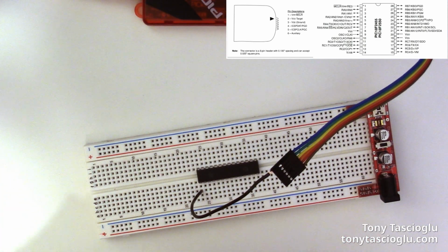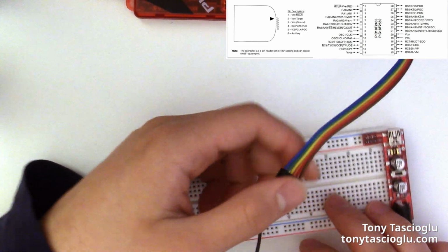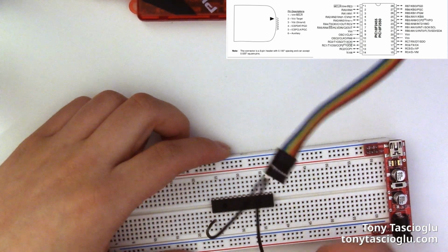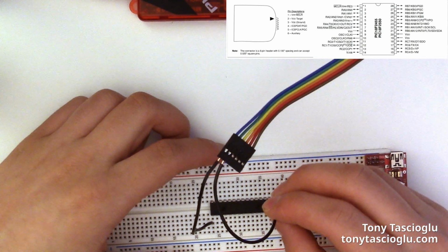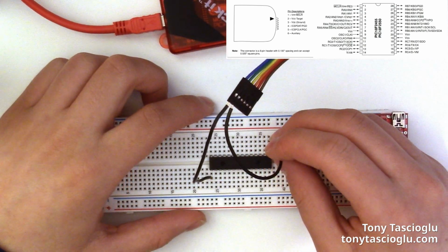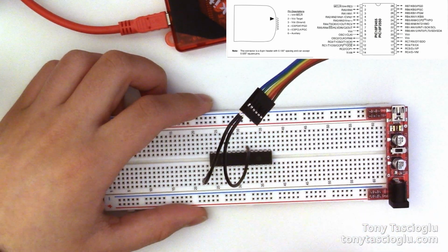Next up, pin 2 is the VDD target. The location of the VDD pin depends based on your IC, VDD being 3.3 volts. For our IC, that is going to be pin 20. Again, look this up in the datasheet for the specific PIC chip that you're using. So, counting pins, you can just connect that right over there to pin 20.